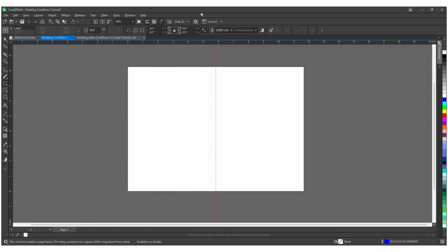Now there is something I like to do from time to time. I must do it on any project. I like to set up my alignment method. And to do that, I just click on this snap to, I check everything. And what that does is, I'm going to show you now. So when I bring the ruler again, it would automatically help me. It will find it. You can see I have not dropped it. I'm just looking for the center, but it's snapping to it. And that's because we were able to check document grid, guidelines, and object here, even guide, yeah, even base grid.